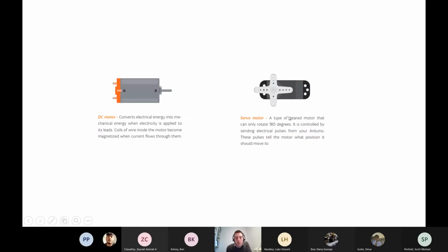And then I guess you are now all experts, or becoming experts, in DC motors, because you've just been using them in your repeatable vehicles. A DC motor is one kind of motor, and that's what you want when you want things just to spin pretty fast. Often you'll have a DC motor combined with a gearbox or some gearing, so that you can trade off the speed for torque and keep the same power.